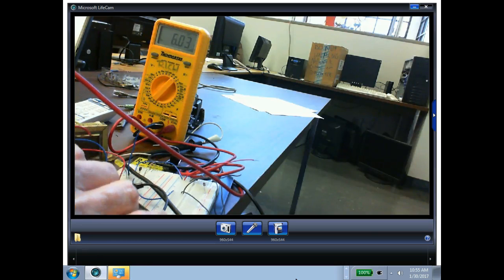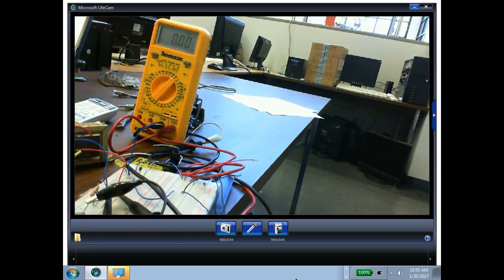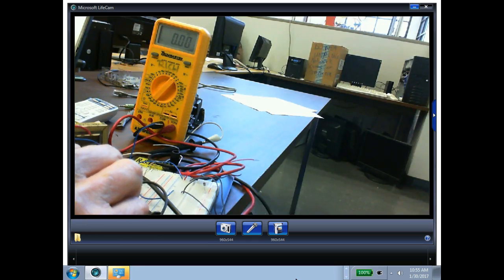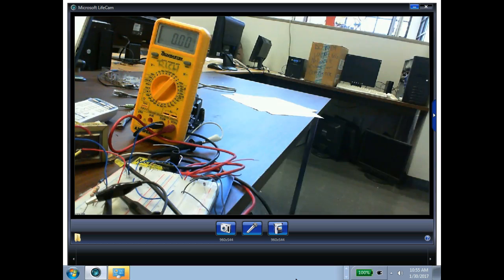Now, of course, what I'm doing, I'm adding more expense. So every time I add something to my circuit, I get better DC, but the power supply becomes more expensive, right? You understand? So it all depends on what you're going to run. This would run a lot of stuff, but if we ran it with a stereo, odds are we would have a humming. So then that's when we start looking at regulation. Depends on what the load requires.